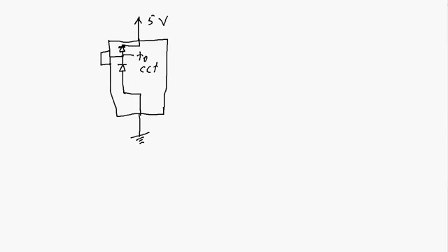And similarly here on the second diode, if the input voltage gets above 5.3 volts or 5.7 volts, again depending on the forward voltage of this diode, this diode becomes forward biased and it clips the voltage that's going to the circuit to about 5.3 to 5.7 volts and protects the circuit from any over voltage.